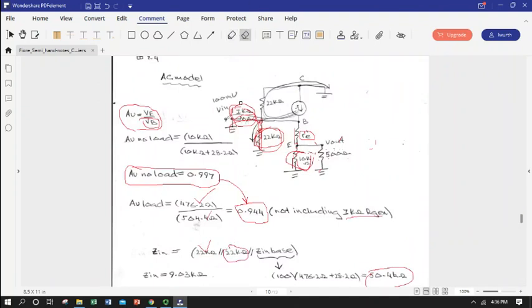So why do we have three things in parallel for Zin? Because when we defined it the last time, there were only two. So remember, input impedance is all the paths a signal can take to ground when it pokes its nose into the amplifier from the input. So we're going to start here. We're going to say, from this point right here, how can I get to ground?